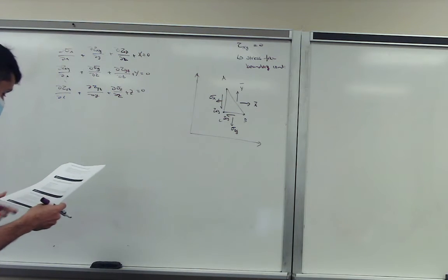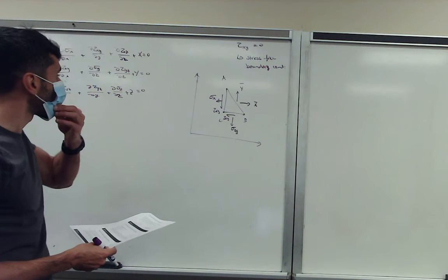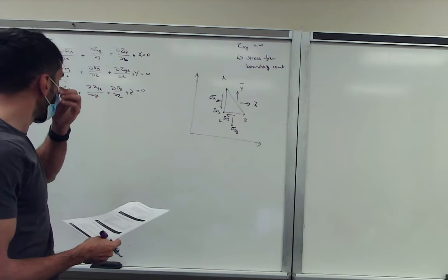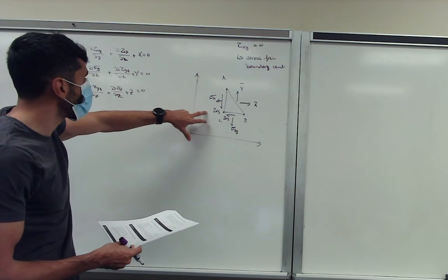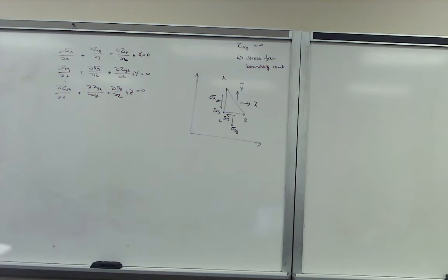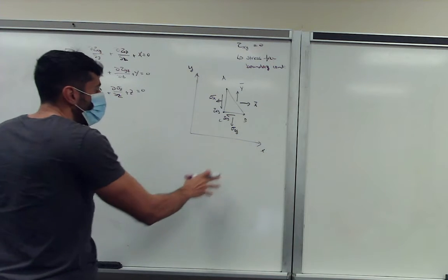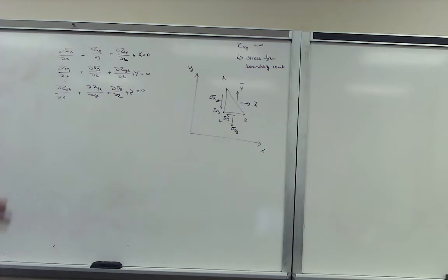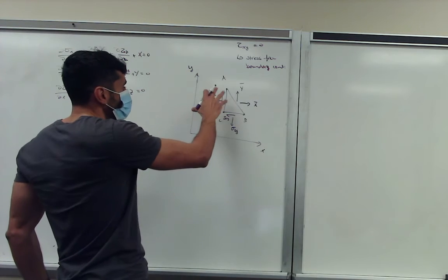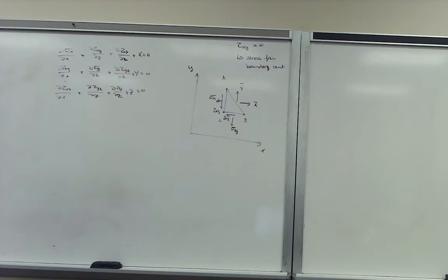So in this case, if you look at this equation, this element, basically what we have to do is equate the shear stresses to 0. We also have to notice that we have now given a coordinate system, xy in this system. But if this coordinate system transforms, so if you shift your element a bit to a slightly different location on your cross section, then you still must have maintained equilibrium.